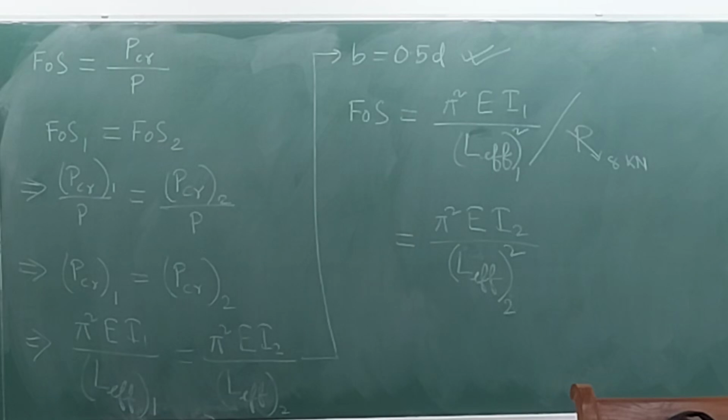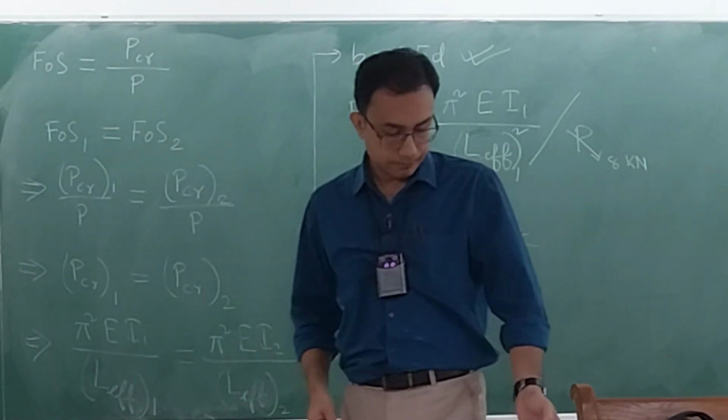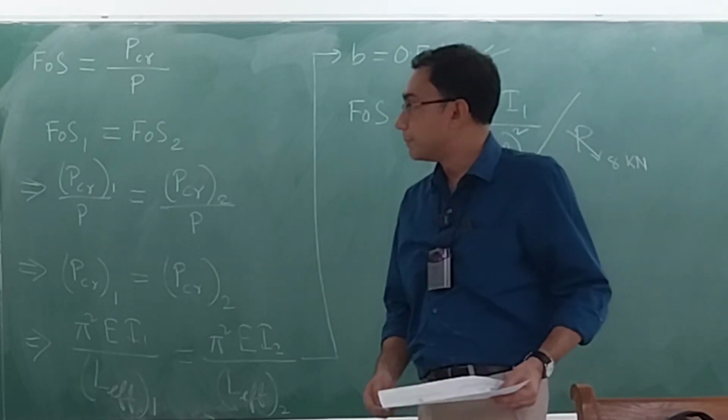So, if you just take a rectangular cross section, okay, and you have the ends just pinned, then it is always going to buckle in such a fashion that the I minimum is the one which is activated. That is all that you have to remember. Okay, the other direction will not even buckle, which is why we use the I minimum thing. Okay. Question number 4.